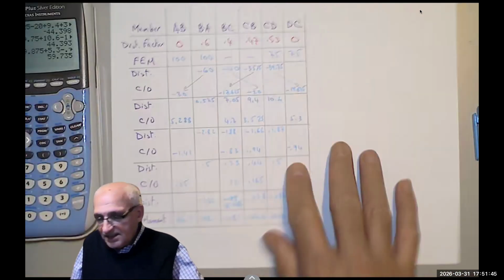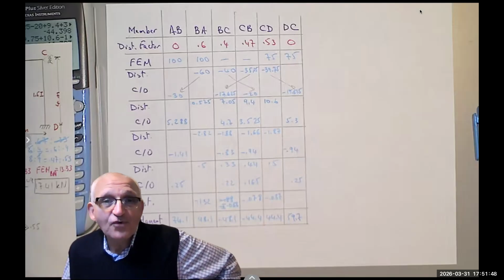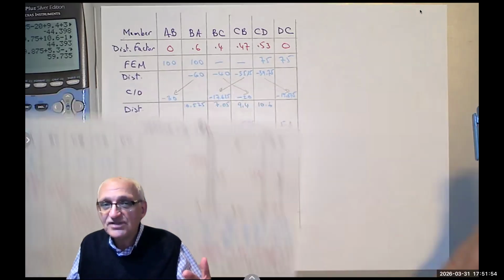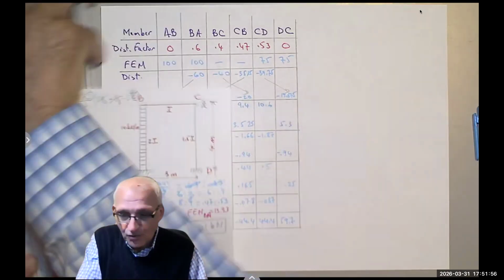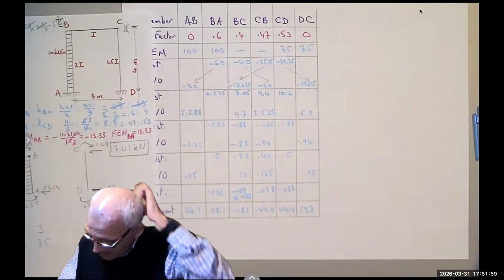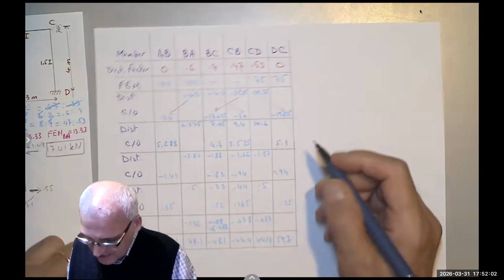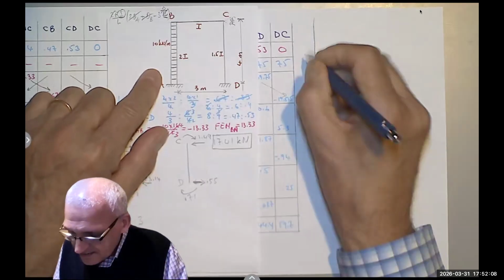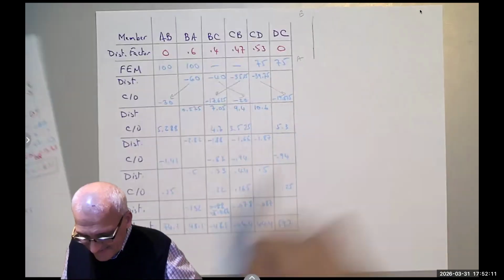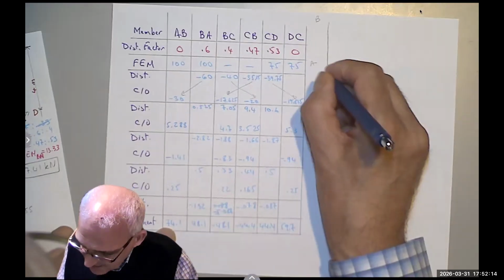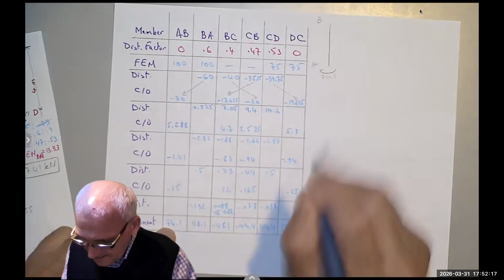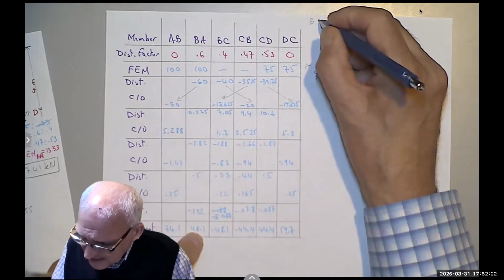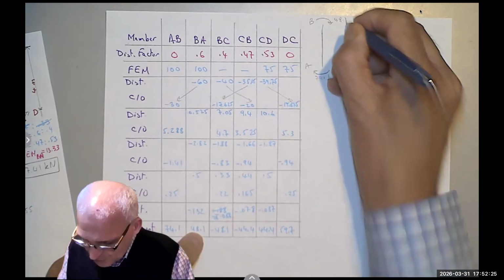Okay. Now we are going to repeat what we did before to find the reaction here, except that this time we don't have loads, we have just moments. Okay, so let's do it here. So I'm going to draw AB. Here is element AB. The moment at A is positive, meaning clockwise 74.1. And at BA is also positive, excuse me, so it's also clockwise 48.1.